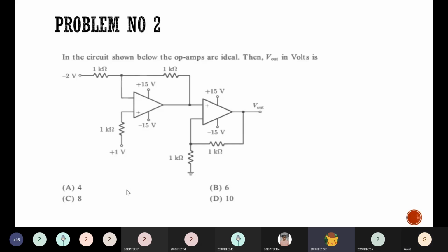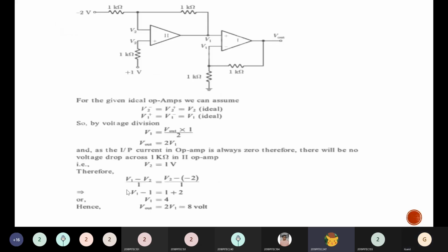Fine, good. I'm showing it. See? First step, you need to calculate the voltage at the output of the first op amp. If you write the equation for this part, they have taken this as the second op amp. This is 1 volt given here, which means the same 1 volt will be available here, which is designated as V2, and therefore the same thing as V2 here also.